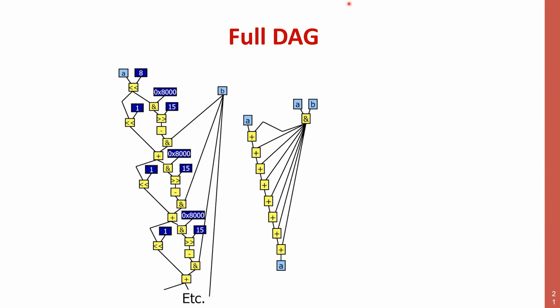So if you think about it, it's an adder, because you had 3 things to add, now you have only 2. One operand to add has disappeared. A bit like in a normal adder, you have 2 things to add, you now have only one, so basically you are done. You have reduced by one the number of things to add.